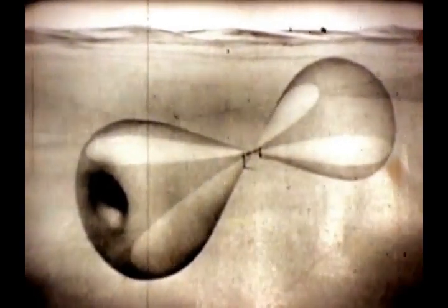Considering one of its planes, such as the horizontal, reveals that it has 4 lobes at an angle of about 45 degrees with the wire. As more half-wavelength elements are added, minor lobes appear, and the angle between the major lobes and the wire decreases. The longer the wire, the smaller the angle.